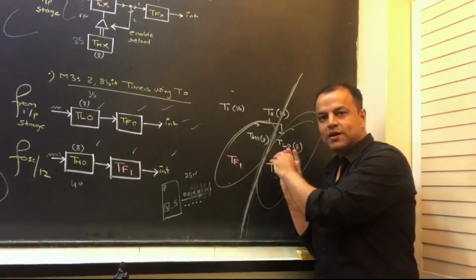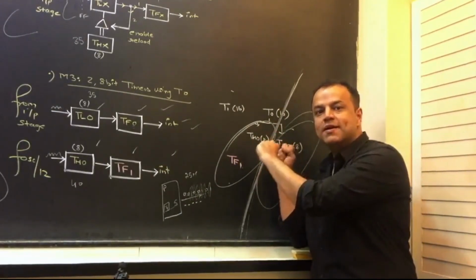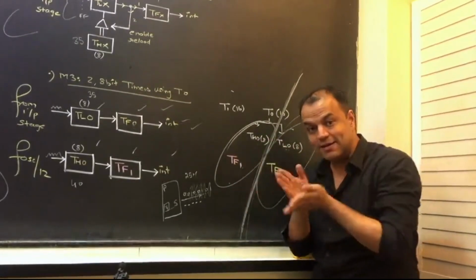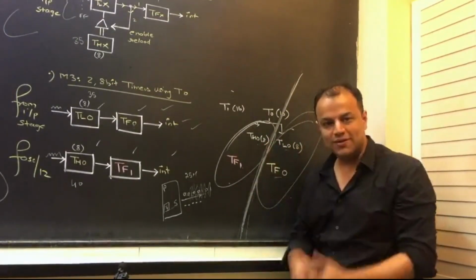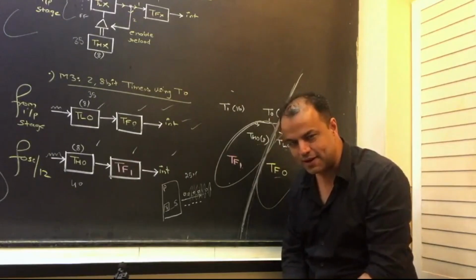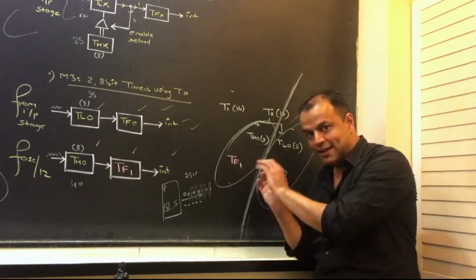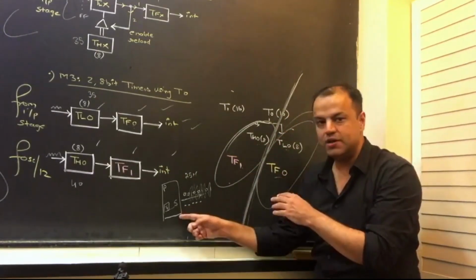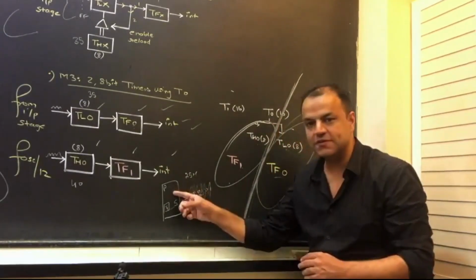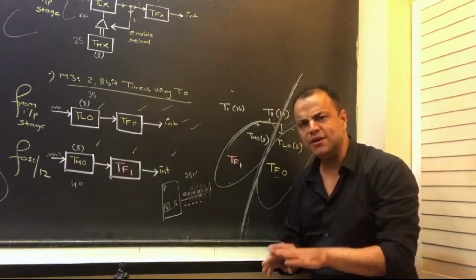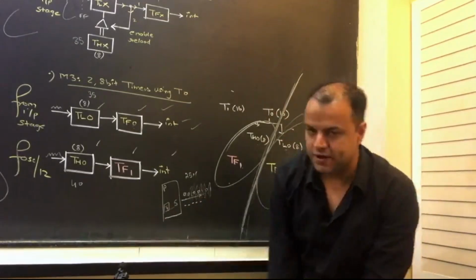So timer 0 lower byte and timer 0 higher byte become 2 independent 8-bit timers. Yes, they are 8-bit, but at least they are independent timers. That means you understand how powerful this chip can get. It is mind-blowing. You can produce 2 delays simultaneously, plus do serial communication, plus the processor is free to do other operations. Did you understand this? Anyway, so that's why they created this mode.